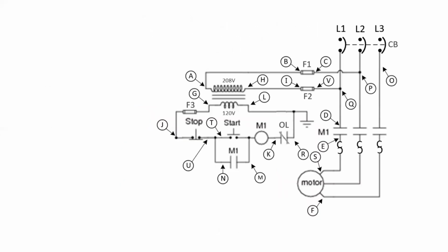When we look at different types of control circuits, different situations can arise. This again is another grounded secondary 120 volt motor control circuit. However, you'll notice that the overload has been located on the right-hand side. In this particular situation, what you want to consider is what would happen if a ground fault were to occur at location K while the motor is running. Well, nothing would happen, as in the motor would continue to operate, no overcurrent device would trip, and there would be no sort of danger to the overall system.